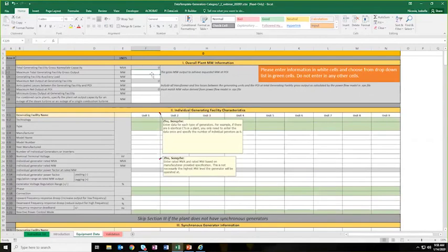This? Yeah, so the maximum plant output for the generator, the question is, are they expected to put in the megawatt value that corresponds to unity power factor? Or what power factor range are they expected to be at to put this value in? We are asking for megawatt. So actually, if the generator usually is operating at a unity power factor, it's okay. But usually we are not expecting it to be at unity power factor, because most of the generators we require dynamic models for.